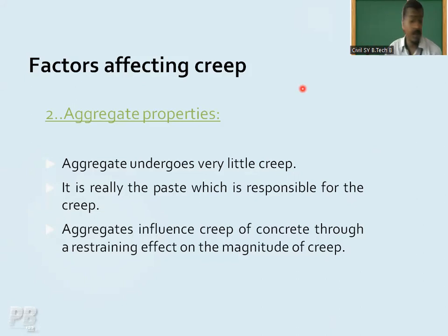Okay. Maybe those aggregates have very low specific gravity. Maybe these aggregates are going to absorb more than 2% of water. Those aggregates are going to absorb more moisture from the atmosphere. Or these aggregates are rounded aggregates, the smooth stones you have seen on a riverbank. Okay, rounded aggregates. Are these suitable to use in the construction sector? Definitely no. We should have angular crushed aggregates having some specific shape and size. Okay.